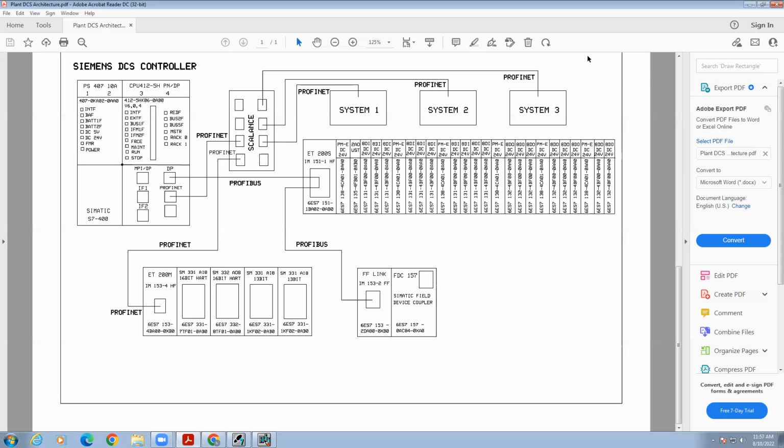While updating, buying the new controller is very expensive, you spend more money and waste more money. That is also a problem during maintenance, because if any problem happens in the controller, you have to spend more money. So the main thing is which controller you want to buy and what your future requirement is. You should have the exact future requirement, select the controller accordingly, leave the protocols for that future updation, and plan all these things beforehand before you buy all the equipment.